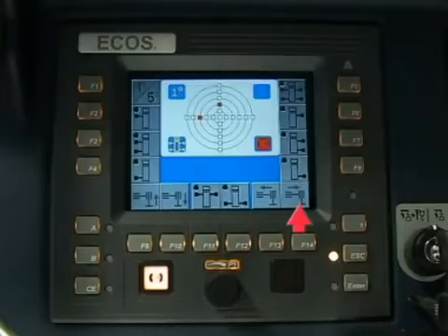For safety reasons, it is only possible to select single outrigger beam functions. When a preselection is made, the outrigger beam and cylinder symbols will change from grey to black to indicate the permissible functions. All preselection buttons have an indicator light to show the selection is active. The preselection is green when active and remains active for approximately 10 seconds to allow a function to be selected.